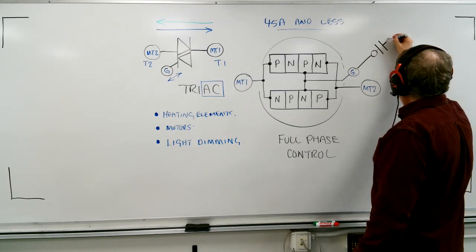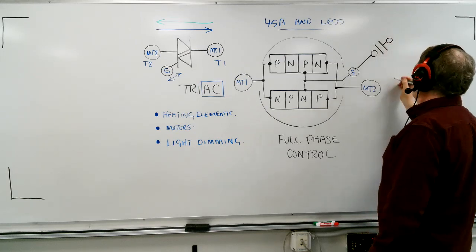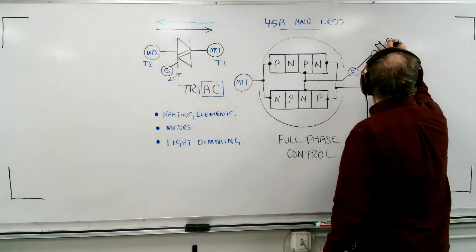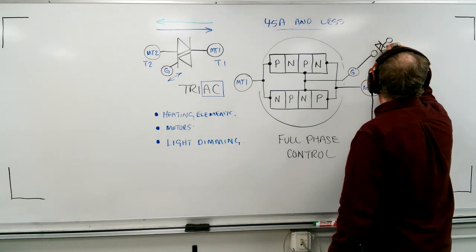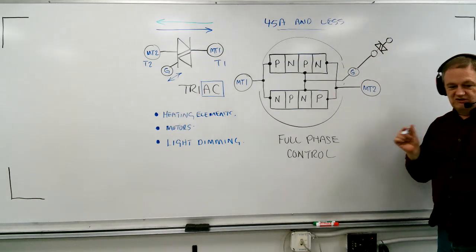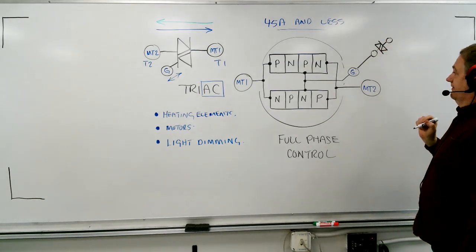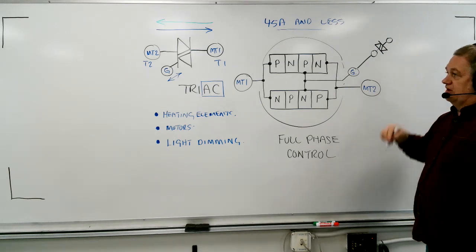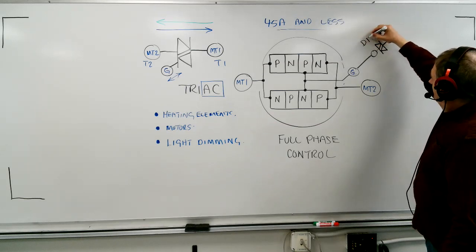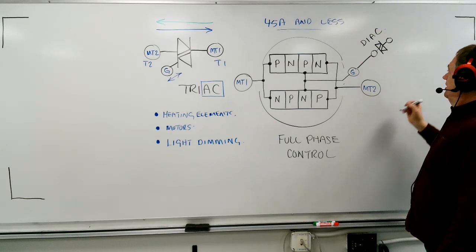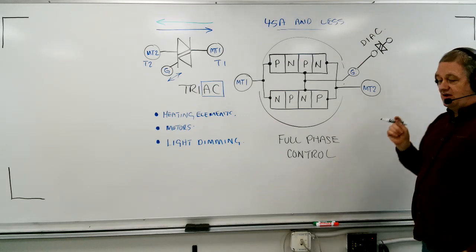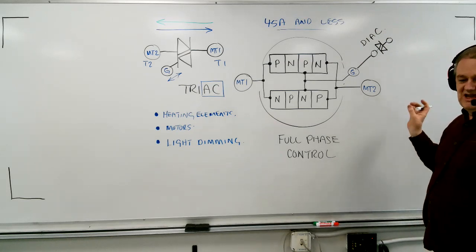And you're probably thinking to yourself right now, okay, that looks like a normally open contact. Hang on, I'm not done. This looks like this, and this looks like this. And you go, oh, wait a second, that's going to be another triac, but it's not. That's where I'm going to stop right there. That's the component right there. And this thing is what we call a triggering device. And this is called a diac. A diac. And a diac has no gate.